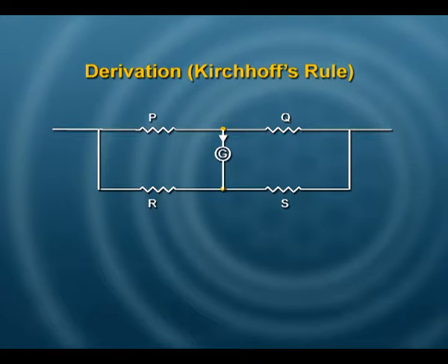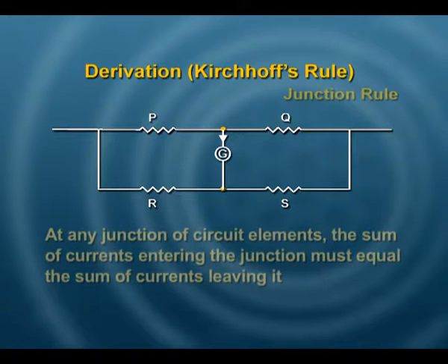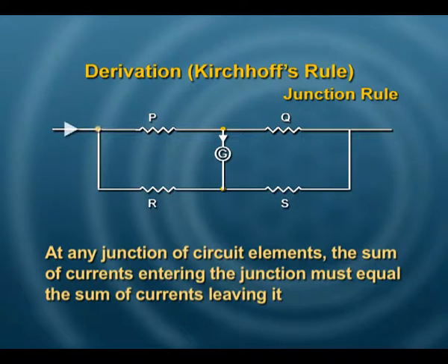something to check the current flowing through this section, like a galvanometer, then there should be no current in the galvanometer. We are going to use Kirchoff's rules to establish a condition for P, Q, R, S for a balanced bridge. What does Kirchoff's law state? The first rule is the junction rule, which says that if a current is entering a particular junction, then it divides into different sections in such a way that this value is equal to the sum of the others. So, how many junctions are there?